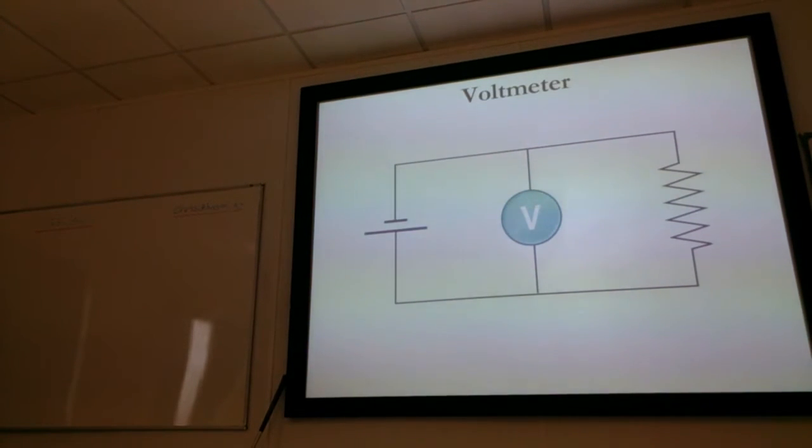Remember the voltmeter's there to monitor the battery and system voltage. We've talked about the on-load check already. If you're discharged, the voltage will drop straight away. If you've got a dead cell, it will go to 0.